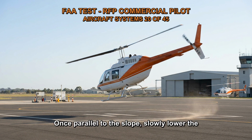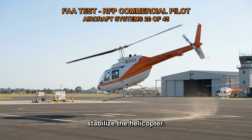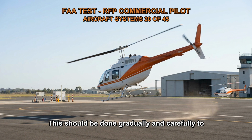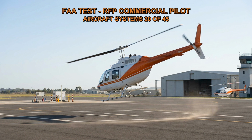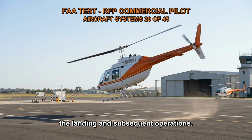Approach the slope at a controlled airspeed and maintain a stable approach path. Once parallel to the slope, slowly lower the upslope skid, the skid on the higher side of the slope, to the ground. This helps establish contact with the slope and stabilize the helicopter. After the upslope skid is securely in contact with the slope, slowly lower the downslope skid, the skid on the lower side of the slope, to the ground. This should be done gradually and carefully to maintain balance and prevent any sudden shifts in weight distribution. By following this procedure, the helicopter can safely land on the slope and maintain stability during the landing and subsequent operations.